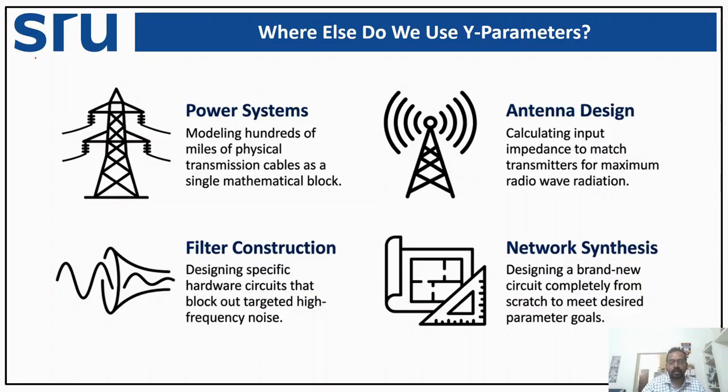The Y parameters are widely used in microwave engineering and high frequency network modeling. At high frequencies, circuits generally exhibit distributed effects, and the current-voltage relationship becomes very complex. Thus, admittance based formulation tries to simplify the matching networks and radio frequency filters, waveguide components, and even antenna feed systems.